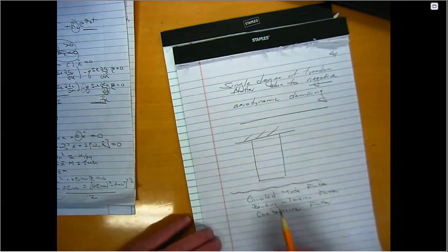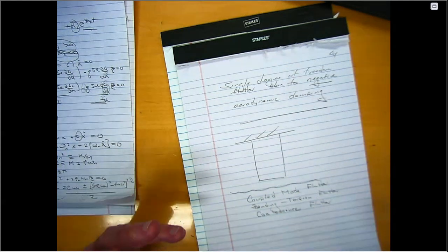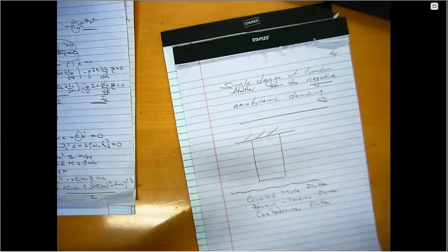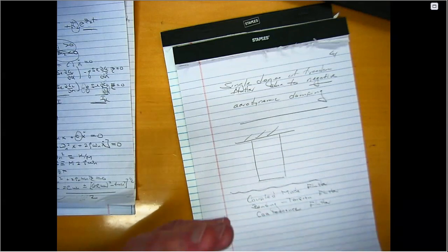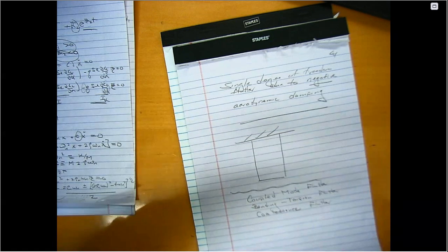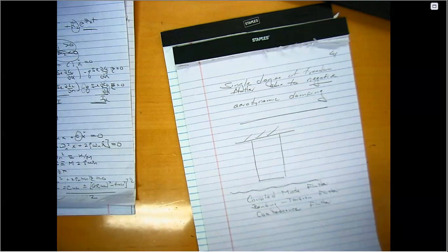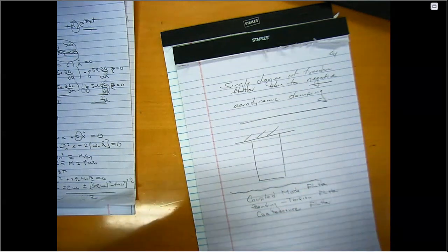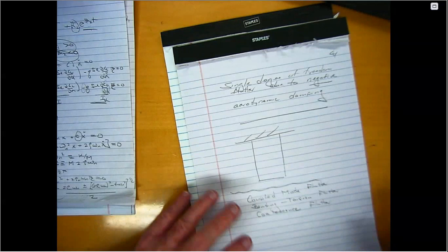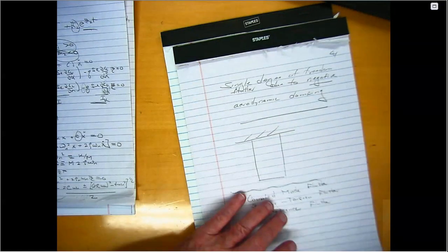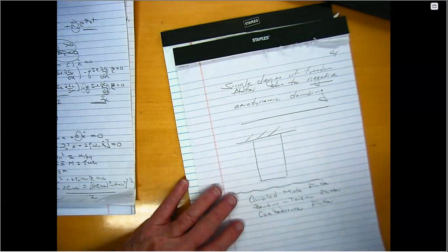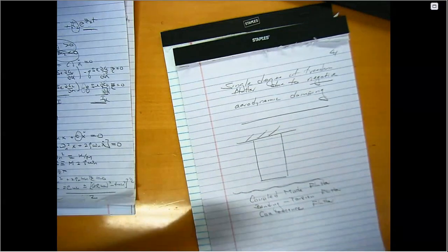The other way you can track in a wind tunnel test, or any experimental test, is to try to track the amount of damping in the mode, right? It turns out measuring the damping in the mode is a lot harder than measuring the frequency, which is not easy either, but by comparison. It's easier to see the change in frequencies than the change in damping, because when you try to measure damping in a real experiment with noise and all the rest of it, the damping values are not very repeatable, and there's a lot of scatter. So I'm trying to plot damping versus Q, and there's a fair uncertainty at any given Q value what the damping actually is. So therefore, I'm having trouble trying to track the damping as it moves along.